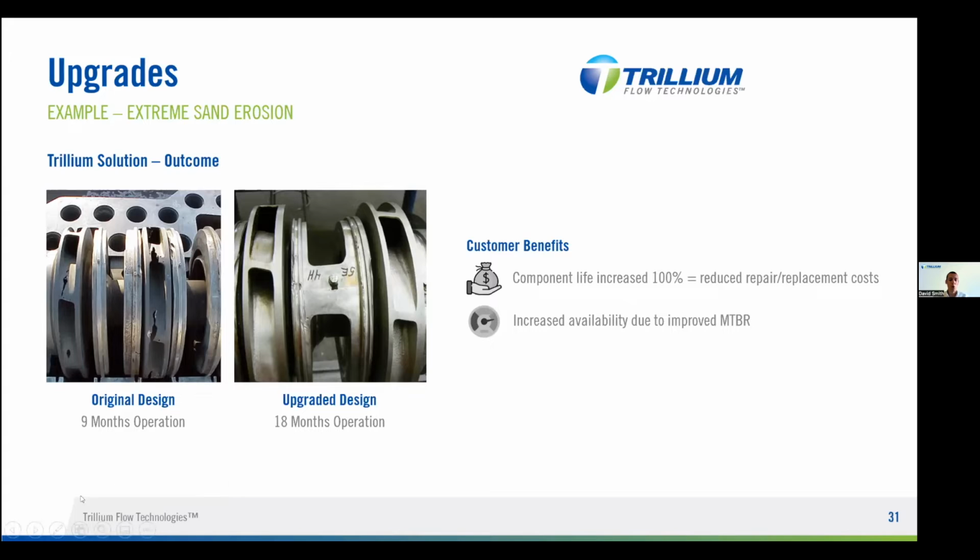If we move to the right-hand side, firstly, you can see in the centre the new wear ring carrier and splitter design. So it's slightly different. But more importantly, you can see the actual condition of the impellers. After this length of operation, we can still continue to operate with these impellers with the material upgrade, and obviously that's been a result of some of the other changes that were made as well.